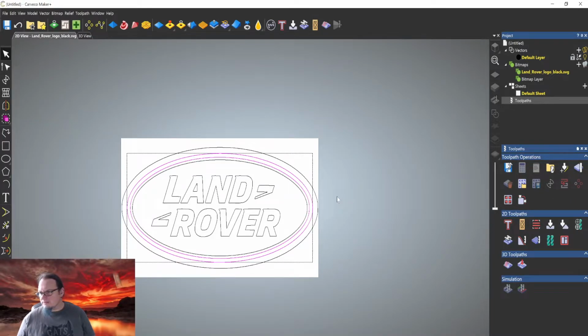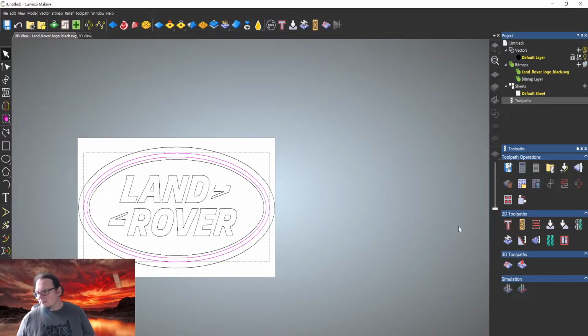Now we're on Toolpaths. This is what we get the options for on this version. So this would have been the same as doing a roughing and a finishing pass in Vectric for 3D. These are our options we want to use here. So what we actually want to do, this will be that create profile toolpath that we're going to use on the outside. Basically follow a line, and then we're going to actually create an area clearance toolpath.